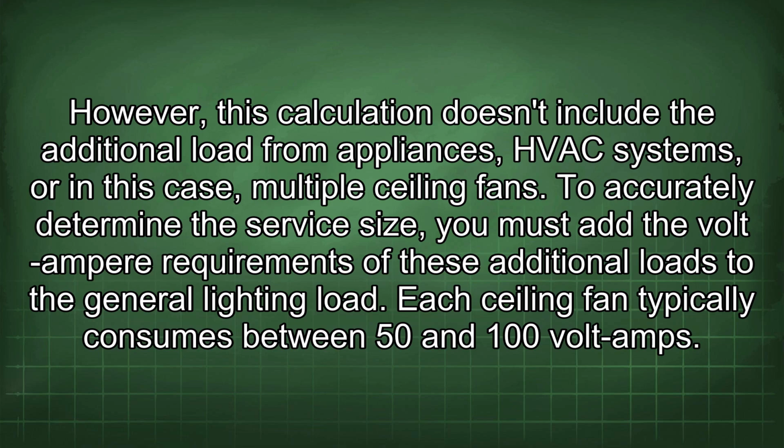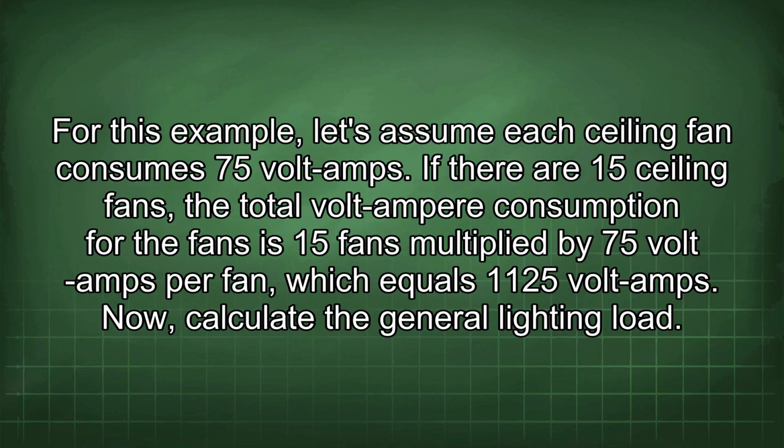load. Each ceiling fan typically consumes between 50 and 100 volt-amps. For this example, let's assume each ceiling fan consumes 75 volt-amps. If there are 15 ceiling fans, the total volt-ampere consumption for the fans is 15 fans multiplied by 75 volt-amps per fan, which equals 1125 volt-amps.